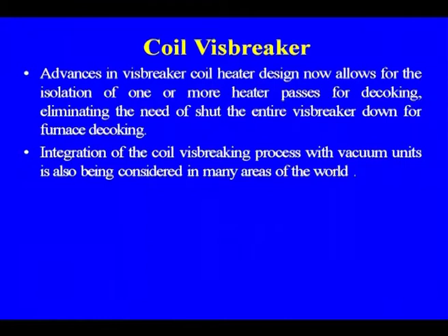decoking. Integration of the coil visbreaker with vacuum units is also being considered in many areas of the world, because of the vacuum residue that will go to the coil visbreaker, and the cracking that will take place. So, this is another development in visbreaking. Now, we have discussed visbreaking, because you see the name itself: visbreaking means the reduction in the viscosity.